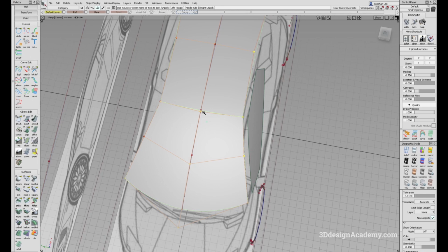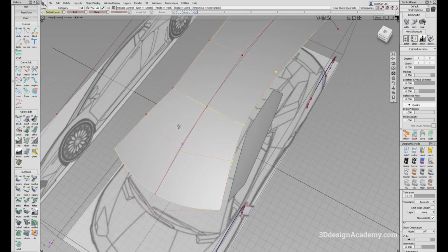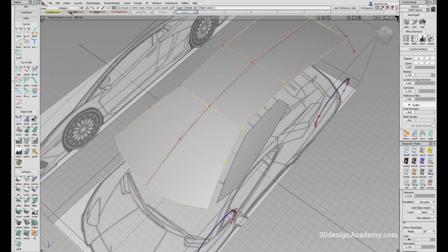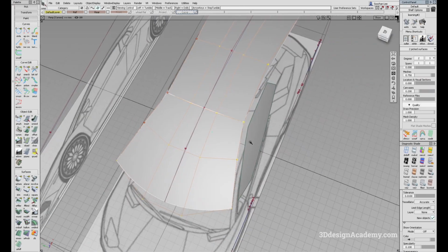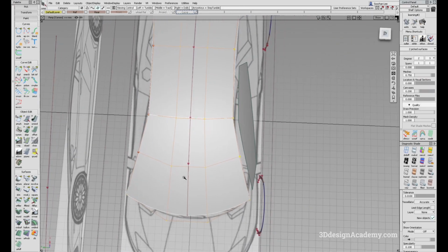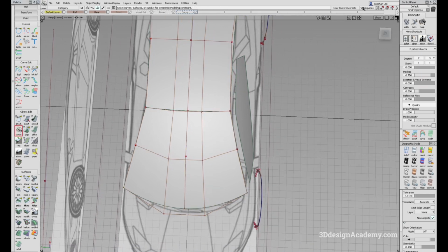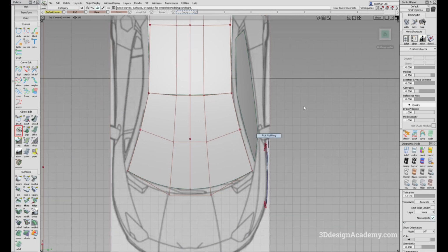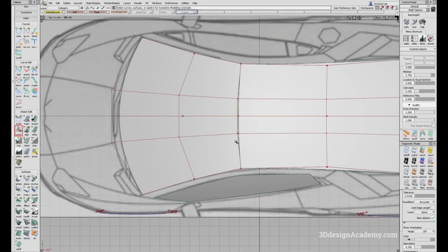And what I'm gonna do is I'm going to add a little bit of acceleration towards the outboard side. So I'm just going to delete the construction history on these, and I'm going to make them degree 3, like this. And I'm going to create a little bit of acceleration towards the outboard side. Okay, so I'm just going to turn symmetry on these pieces over here. And actually, let's just go over here.